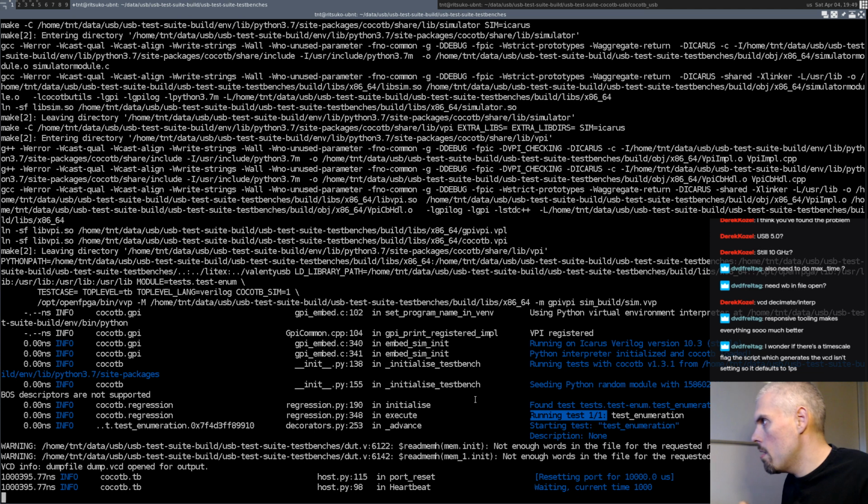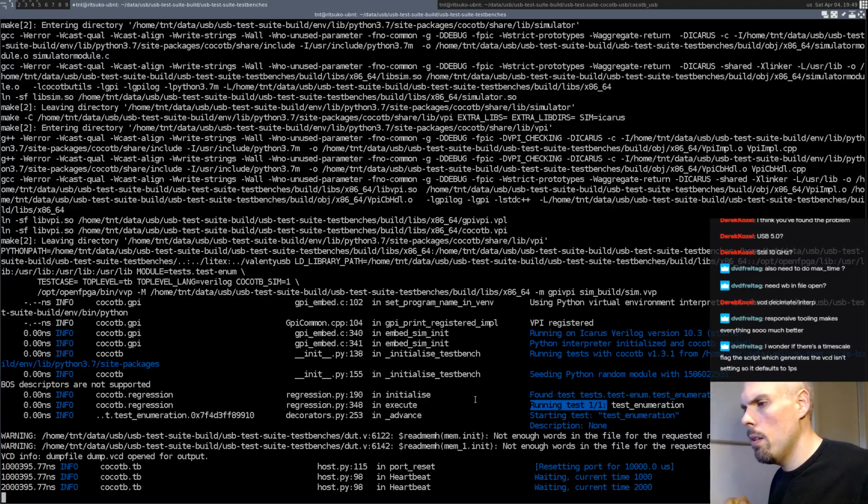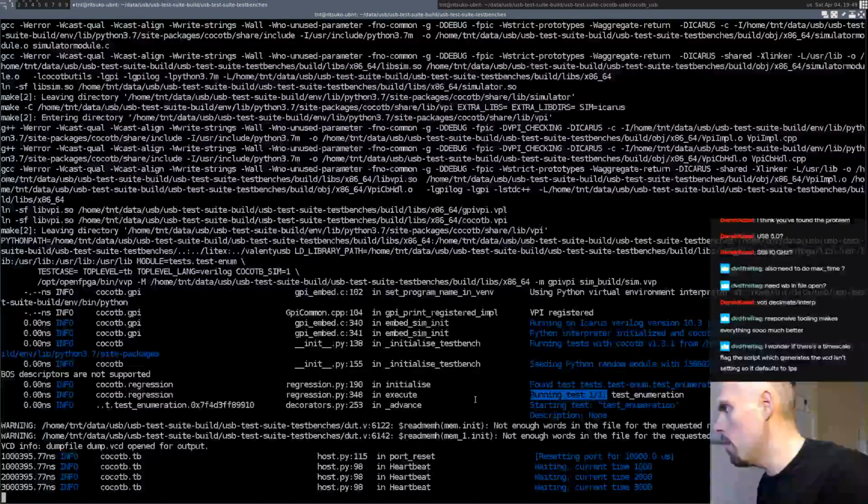For me, the simulation still takes a bit of time to run. Well, it's not too bad. I wish there was a faster simulator. Actually, White Quark just updated her CXXRTL thing. I haven't tested that yet. Has anybody tested that? I don't know if in the chat here. It's in the same style of Verilator, where you take Verilog and compile it to C++, and then you compile that C++ and run it as native code for simulation.